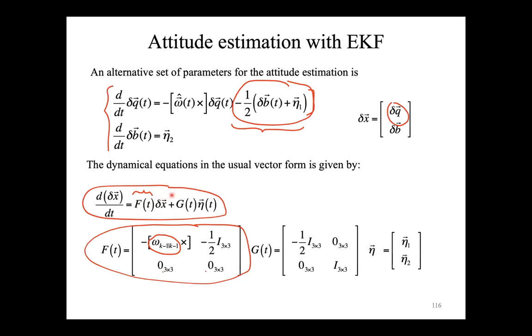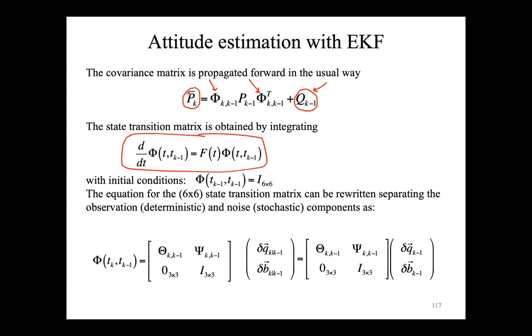However, as I said, if you look at the appendix, you have an additional term that in that part is called the U. So it is an additional term to the differential equation that is not directly related to the state, but is related, for example, in this case, to the gyroscope error. So what we are going to do is that when we want to compute the covariance matrix, where we want to propagate the error, we don't need only the covariance matrix at the previous state, but we want to also propagate the error associated to the quaternion, to the gyroscopes.